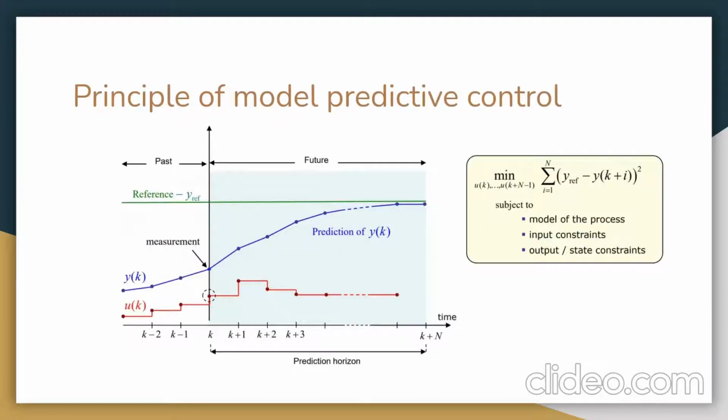In principle, Model Predictive Control minimizes the cost function over a limited prediction horizon by solving an optimal control problem until that horizon. As a result, MPC calculates a plan of control actions that collectively minimize the cost at a finite horizon.